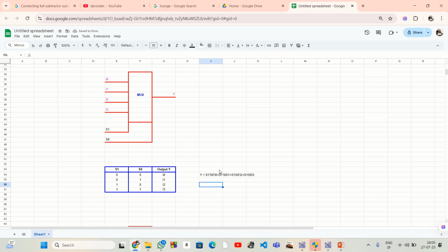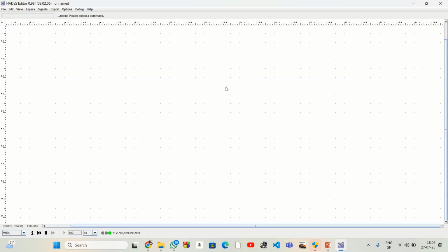The next thing that I need to do is to design the circuit of this multiplexer. We will launch headers like this. Then over here I'll have some input switches. I'll create these input switches here. I'll have 1, 2, 3 and 4, and their values are I0, I1, I2 and I3. Then down here I will have the selection lines S1 and S0.